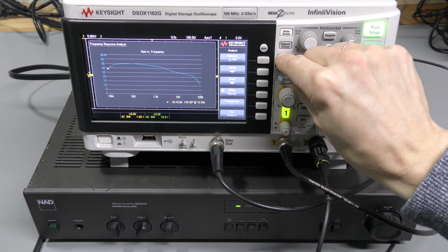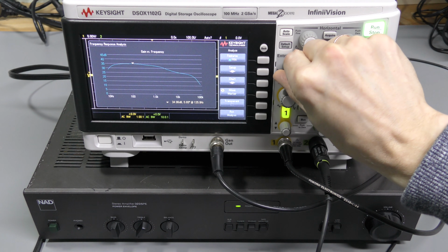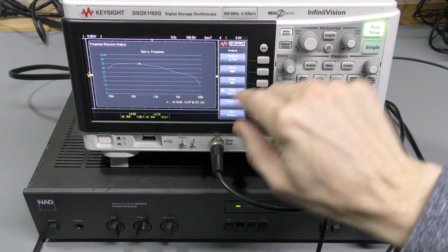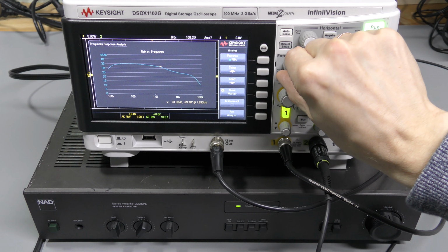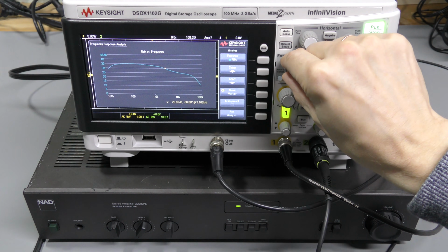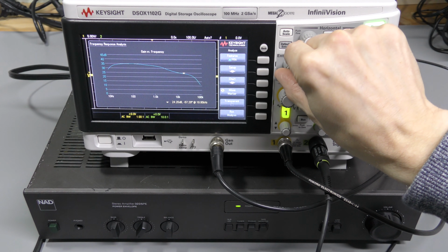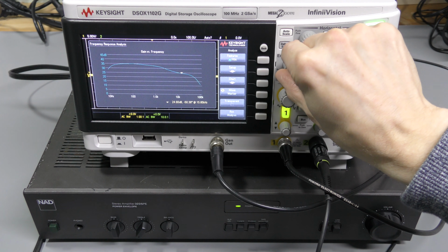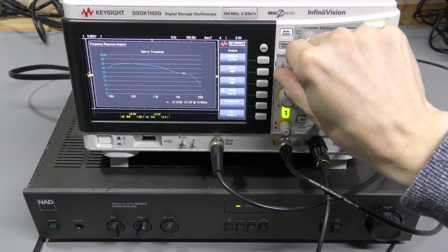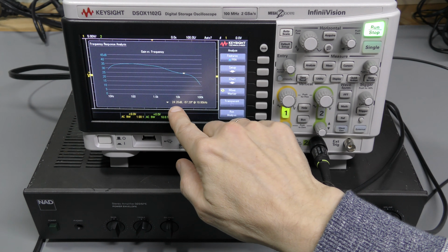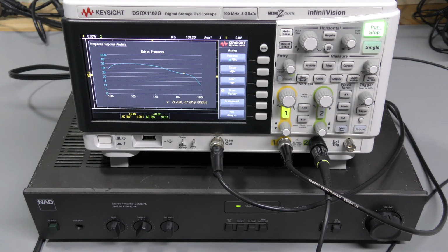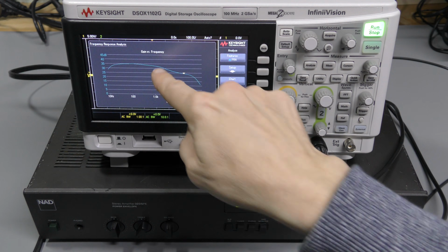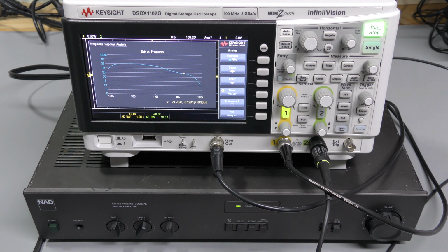Now let's cut high frequencies and run this again. Here we are. This time it gradually dropped from around here, which is 250 Hertz, and it started dropping steeper around here, which is about 2 kilohertz, and here, around 15 to 20 kilohertz, we measure about 24 dB, which is again about 10 dB different from the baseline. Looks great.